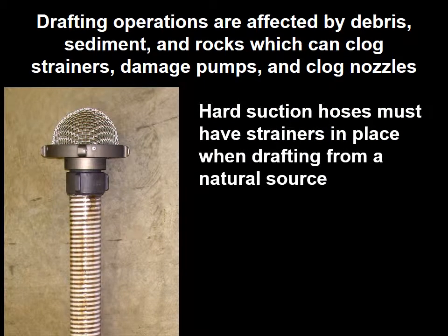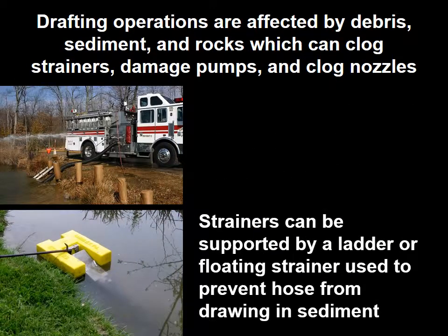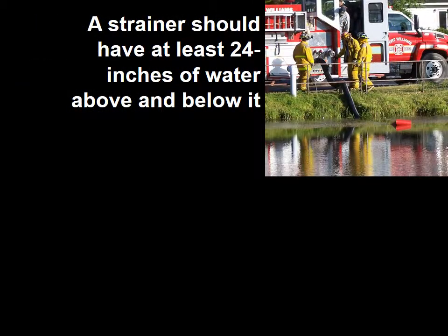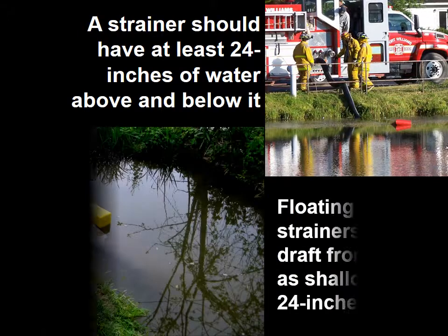Strainers may be supported by a ladder, or floating strainers may be used to prevent the hose from drawing in sediment. A strainer should have at least 24 inches of water above or below it. Floating strainers can draft from water as shallow as 24 inches deep.